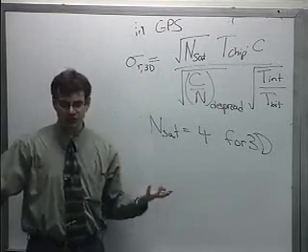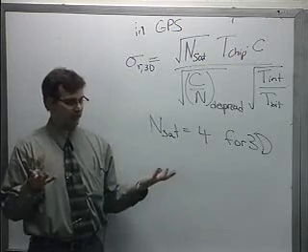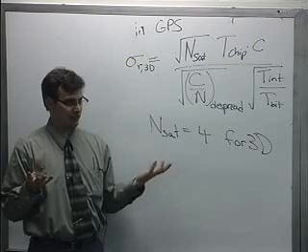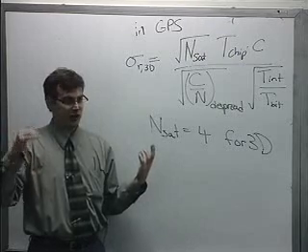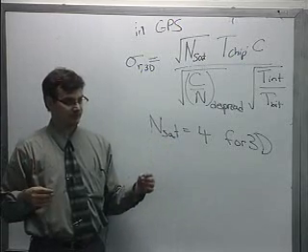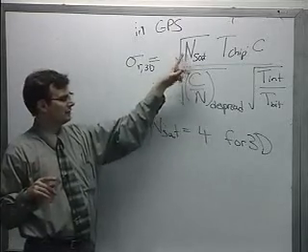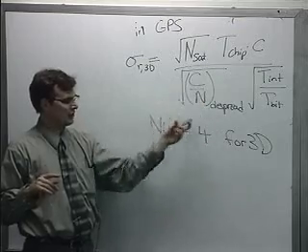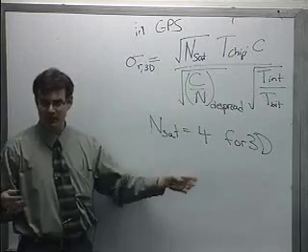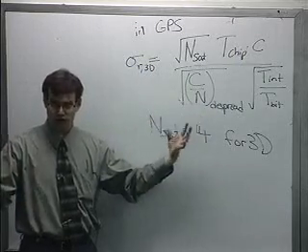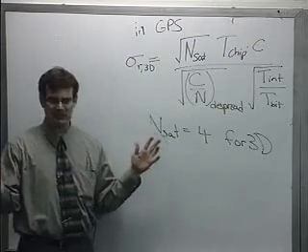If you have an extra satellite, your GPS receiver has to come up with some sort of new algorithm for how to handle that extra information. In some cases, it'll just take the ones with the highest carrier to noise ratio and throw the rest of them out. Well, in that case, you put N equals 4 and you use sort of the average carrier to noise ratio. Or if you have some more clever way of using that information in a mathematical algorithm, you have to sort of derive a new Cramér-Rao bound for that particular case. Does that make sense?